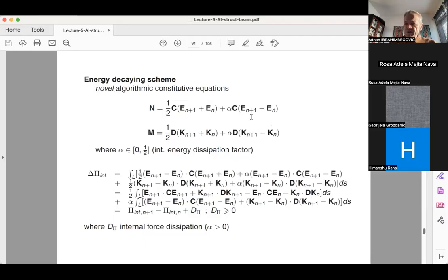The rationale for that is basically if you have high order frequencies, as opposed to low order frequencies, the time step is different. For low order frequencies, you have a very small value of omega, and very large value of the period T, because it's 2 pi over omega. Omega being small, the corresponding period is very large.